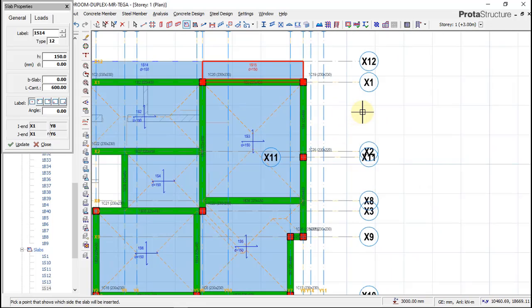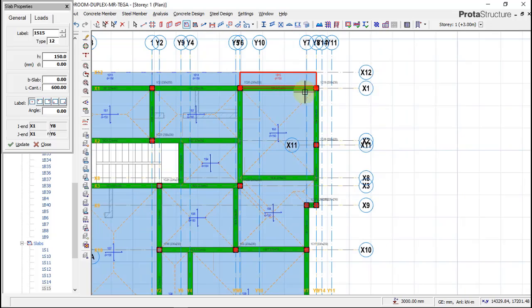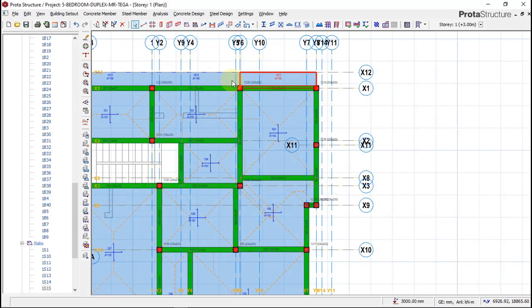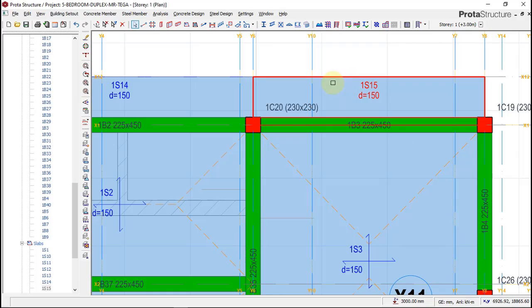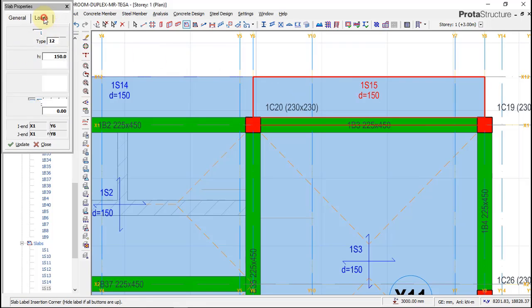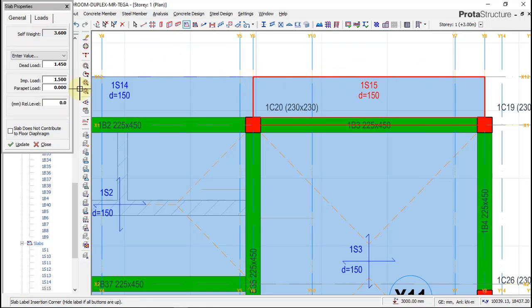And then, okay, we notice that we have not put our cantilever load. So I'll quickly edit one of the cantilevers. Our cantilever load, which is the load on the edge of this cantilever, is 9.81 kilonewton. So I'll quickly say update, and you can see the symbol of our load.